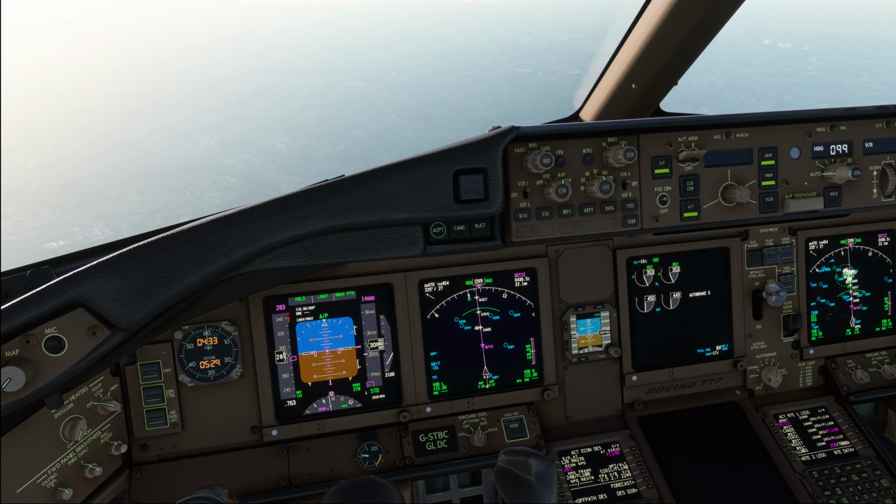Now, as someone who flew short haul for 5 years on Boeing aircraft, I would of course increase the target speed because that reduces total flight time and therefore would reduce the overall cost of the flight, since you have less time that the engines are running and therefore less fuel usage.